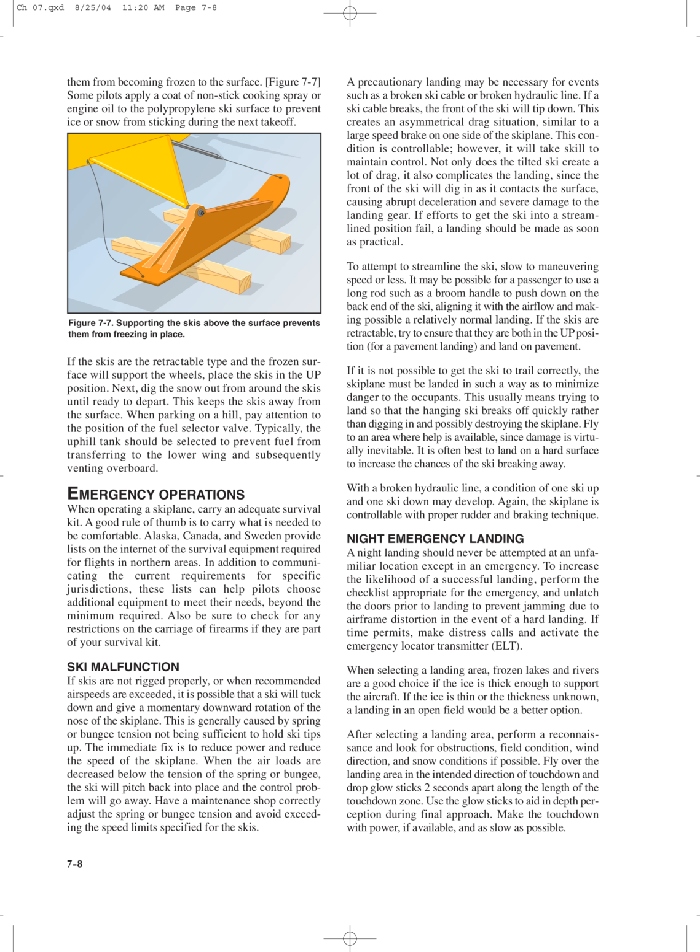When parking on a hill, pay attention to the position of the fuel selector valve. Typically, the uphill tank should be selected to prevent fuel from transferring to the lower wing and subsequently venting overboard.